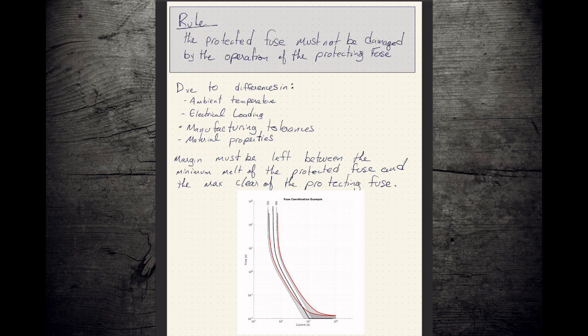So, did you get the fuse where the fuse element's a little bit short and the solder's not very thick, and so it's going to operate a little faster? Or there's a nick in it, so now there's a weak spot in the fuse element? Or did you get the fuse that had the chunky fuse element and they really gobbed the solder on it and got a solder ball stuck in the middle, and now that's acting as a heat sink and it's going to slow your fuse's behavior down a little bit.